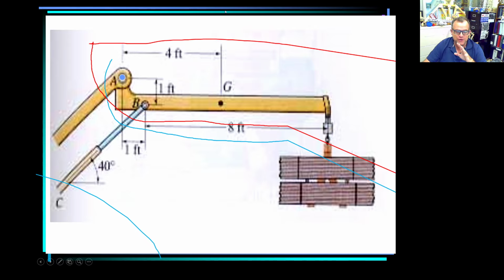So I'm gonna use this and look only whatever is outside that thing. This thing here, what type of support does that look like? A pin? Yes, that's a pin support. Now, a lot of people are gonna say, oh, this is another pin. Well, now be smart. If you have 2 pins, you have 4 unknowns. You cannot solve it in the statics.